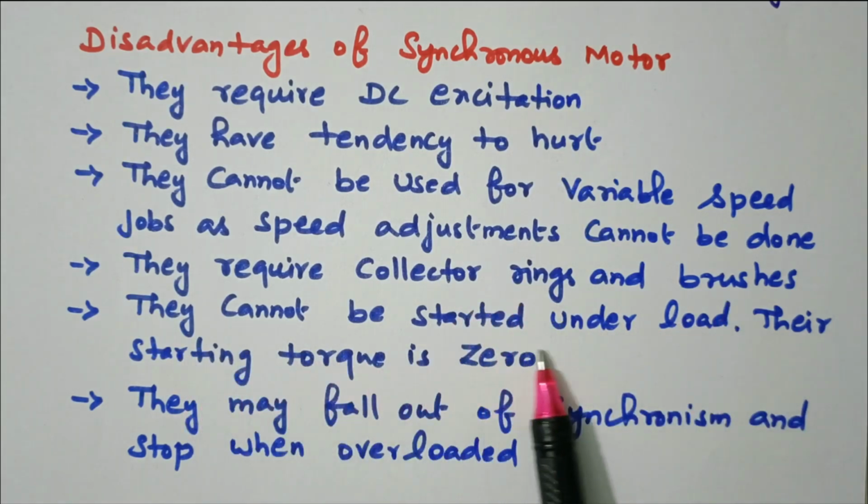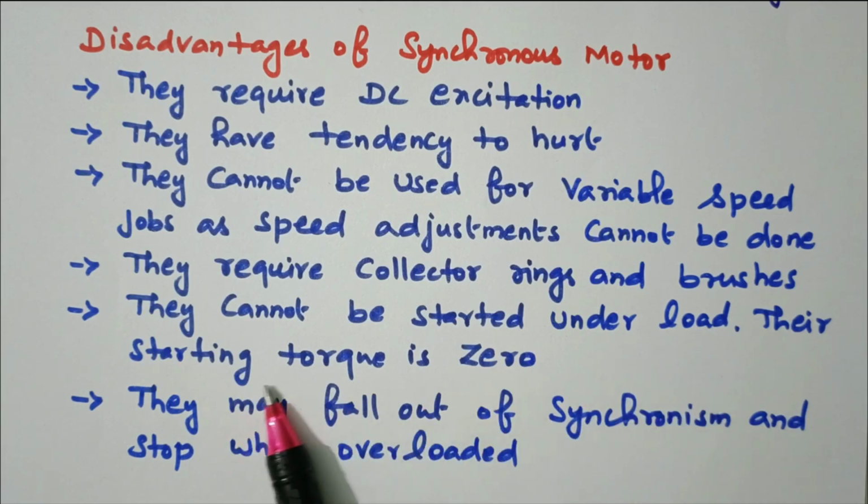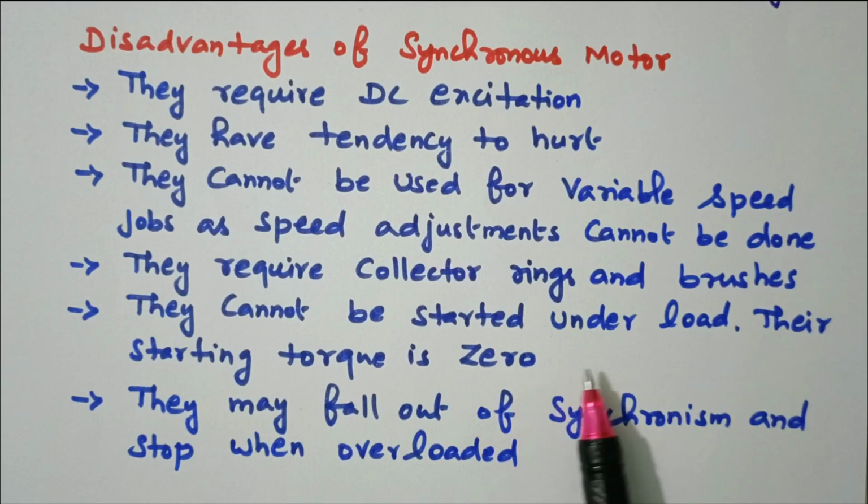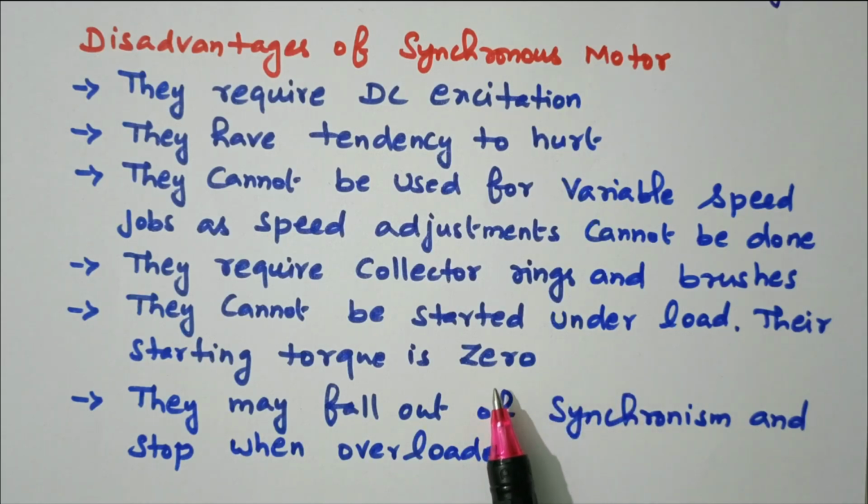They cannot be started under load. Their starting torque is 0. So under load we cannot start, because starting torque is 0. They may fall out of synchronism and stop when overloaded. So during an application, suppose it is overloaded, it will stop. The motor will stop.